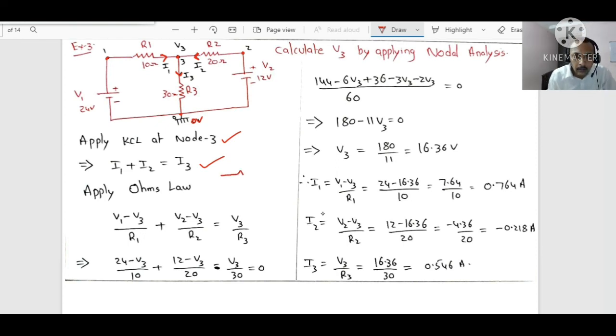So because of that, observe, if this is the resistor R1, here the voltage is V3. Okay, good. But here the other end is at plus V1. So this voltage is V1. Now if I want the current through here, I1, it is simply (V1 minus V3) by R1.